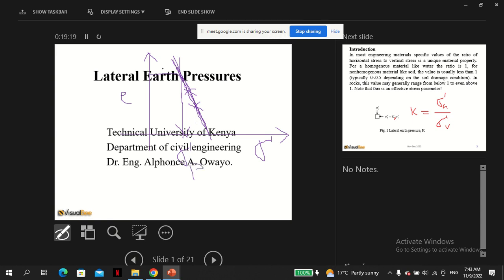So if you consolidate with any value here, you can see that this value is less than sigma p, and the state of the sample will not be on this line. So that's why the value you use for consolidation must at least be equal to, or slightly higher than, sigma p. So for reference purposes, the value for consolidation is always equal to the pre-consolidation stress. You can add a few kilonewtons, 1 or 2 higher than the pre-consolidation stress. Okay, so please note that.